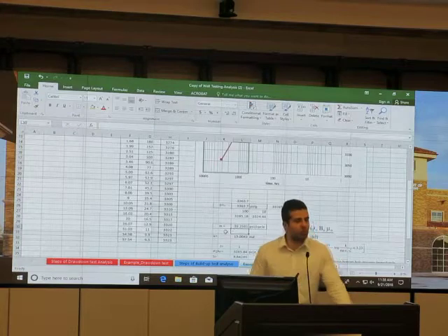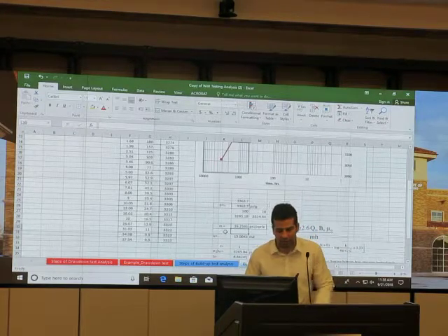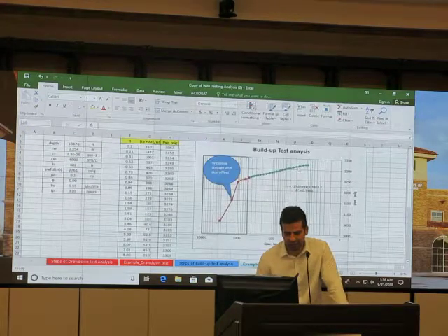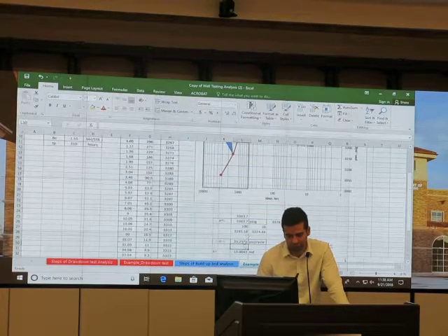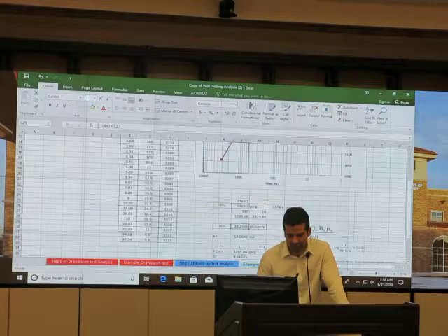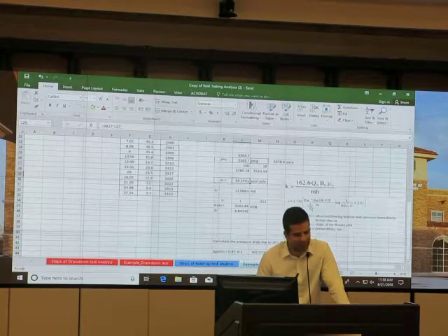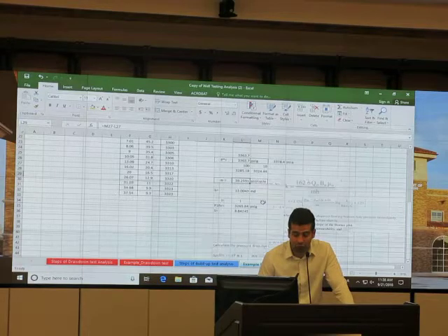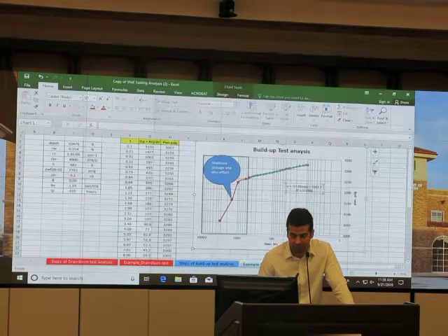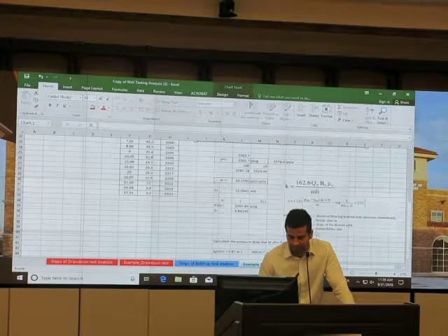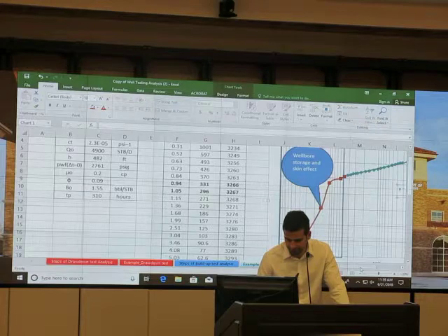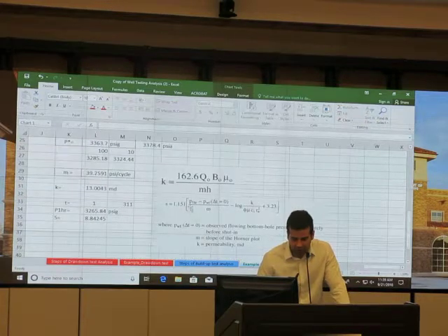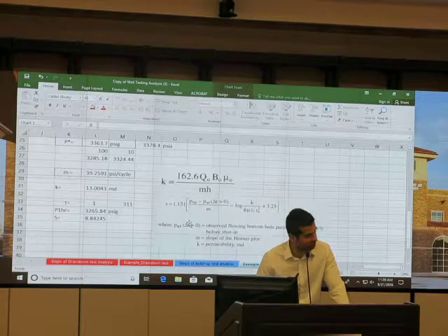But Dr. Amadi here used one cycle and used 2 points. And the data is pretty clean over here, so it shouldn't be any problem. 2 points also work. So you get the m, you put m over here, you calculate the k, you use that one-time cycle, you use the equation that you got from here, you calculate the pressure at 1 hour, again using this simple equation, you get the skin factor, and that's all.